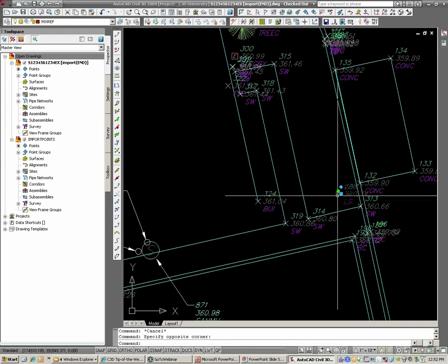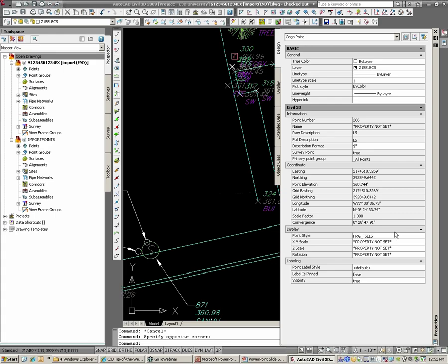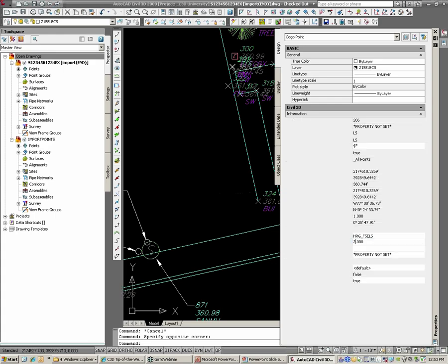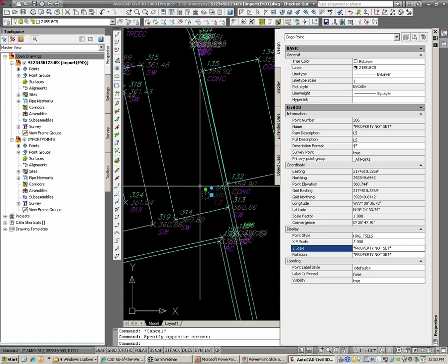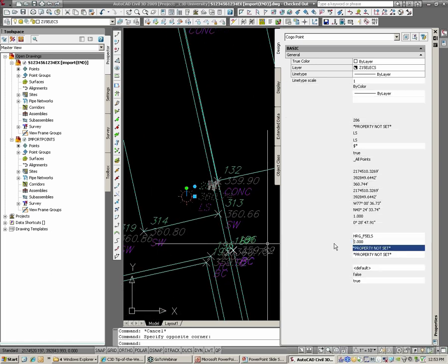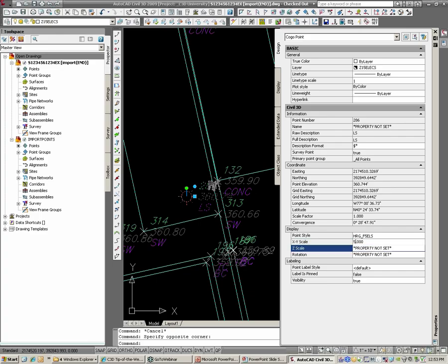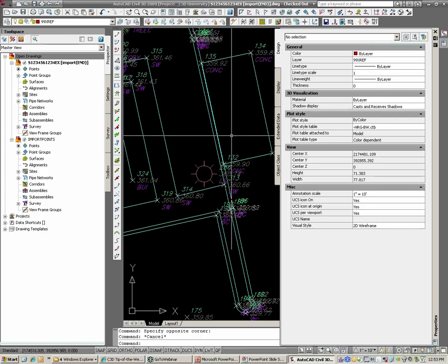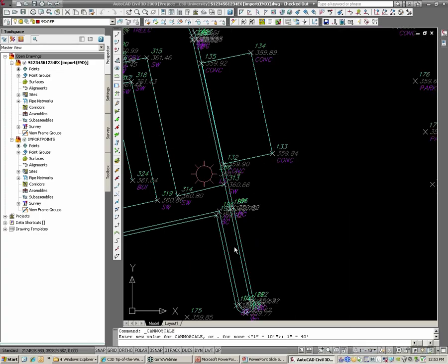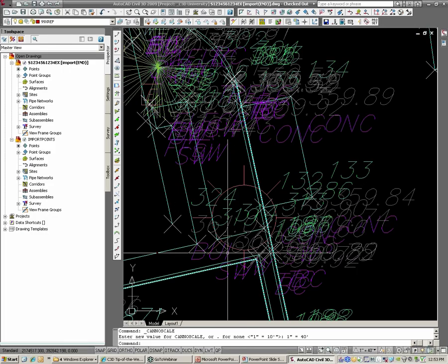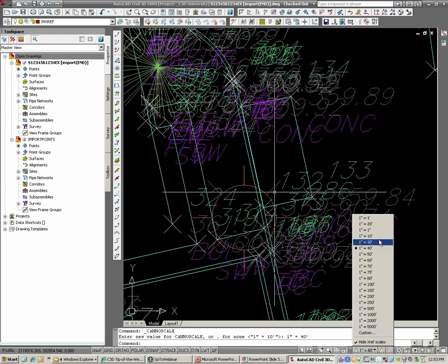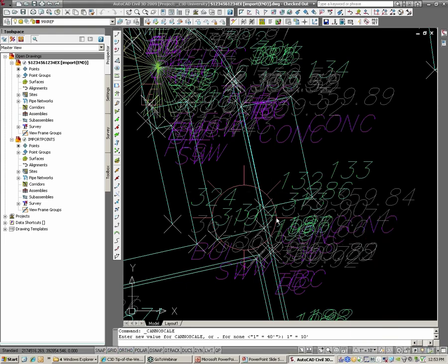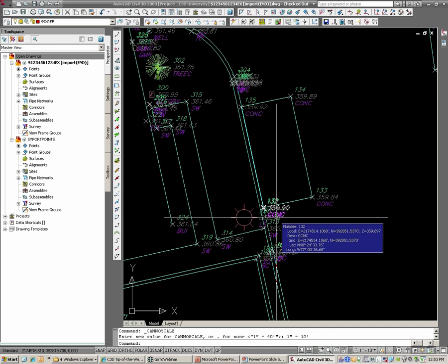And that also works for the adjustable symbols. Whereas if I wanted this light base, say at 10 scale, that's what our drawing set is, but I want the light bases to be a little larger. I can go in, and I should have moved this over before I did that. Sorry. I can go in and say I want the light bases to be 5 times the size, because I just want my light bases to be really big. I mean, it's a lighting plan. It's very lighting oriented. They still auto scale, so if I change it to 40 scale, it keeps that 4 times larger than what you brought it in at. So that's something that people miss.